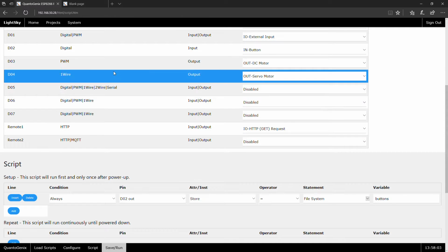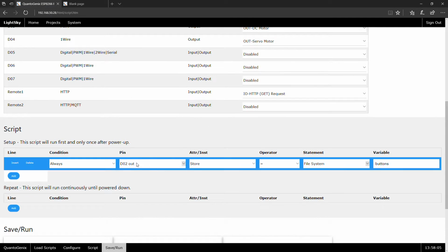What we do want though is the timer. So we have declared the timer and it comes up as timer 1 out. And you'll see we have start value, stop, and once again store. Now store will only mean that, if we specify the timer should run every 10 seconds, it's going to write into the file every second that it hasn't run yet, it hasn't run yet, and after 10 seconds it's going to tell you, okay, the timer has executed.